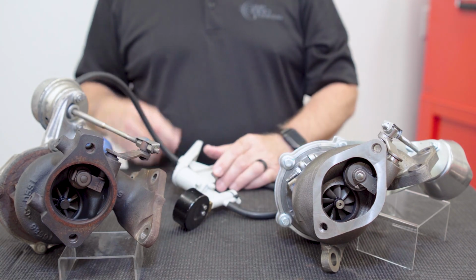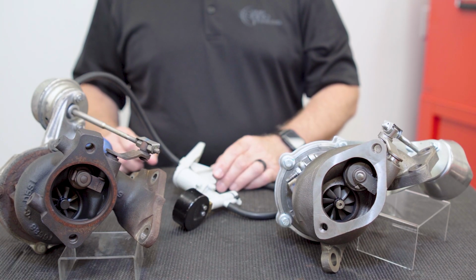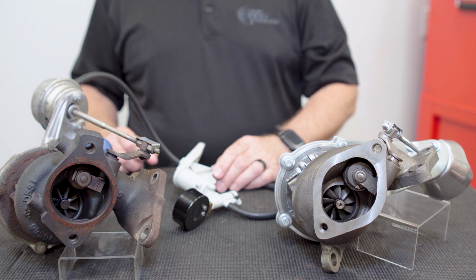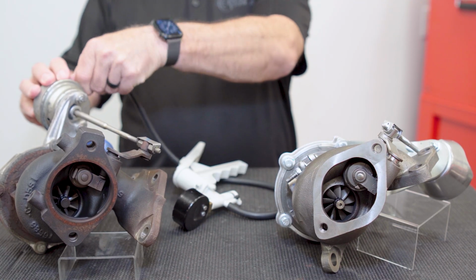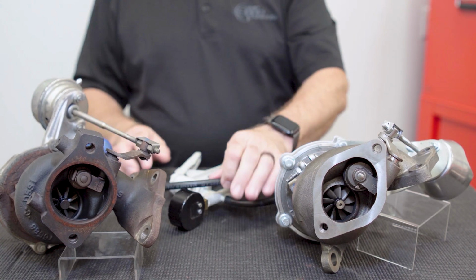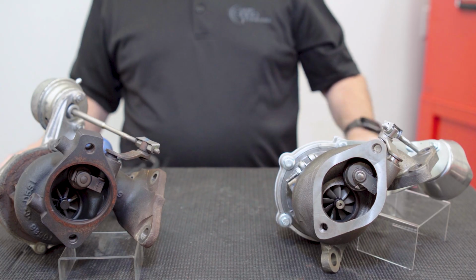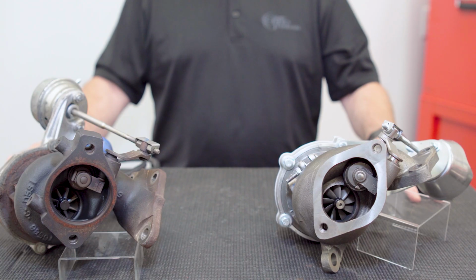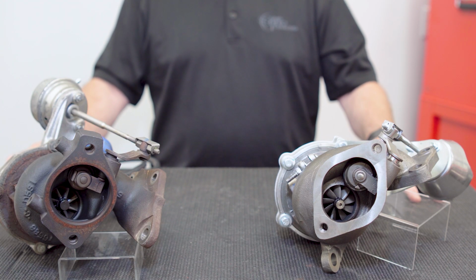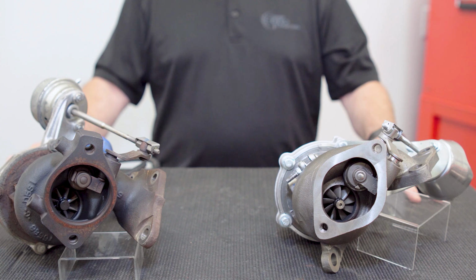All right, and with that, Corey, we'll hand it back over to you. Fantastic. Thank you, Mark. Yeah, that's just one of those things where it gives us an opportunity to, without tearing everything apart, just make sure that the wastegate actuator is at least working. Now, if we don't see the changes that we're looking for on the scan data, again, like you said, we need to go a little bit further. We're going to have to tear some things down. But fortunately, in this case, if we did have the scan data matching what we were doing, like you just did with the hand pump, at least we know we can eliminate one piece of the diagnosis and move on to something else. That's exactly right, Corey.